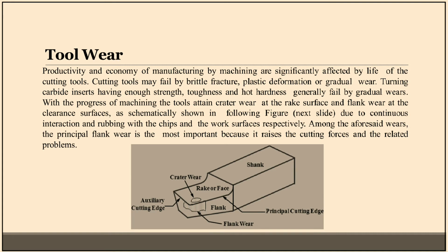With the progress of machining, the tools attain crater wear at the rake surface and flank wear at the clearance surfaces, as schematically shown in the following figure, due to continuous interaction and rubbing with the chips and the work surfaces respectively. Among the aforesaid wears, the principal flank wear is the most important because it raises the cutting forces and the related problems.